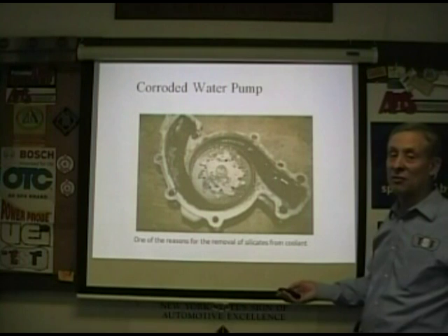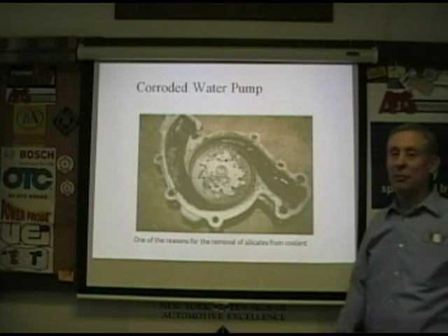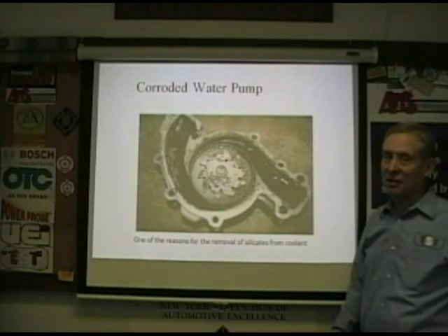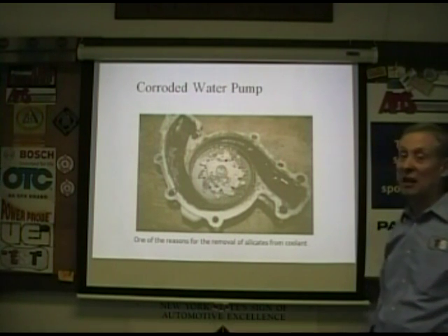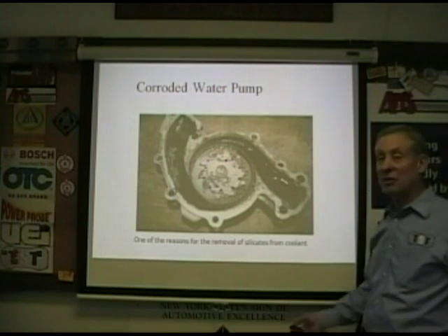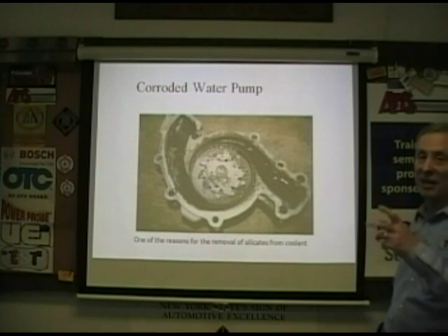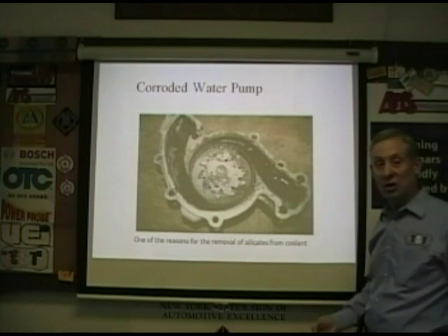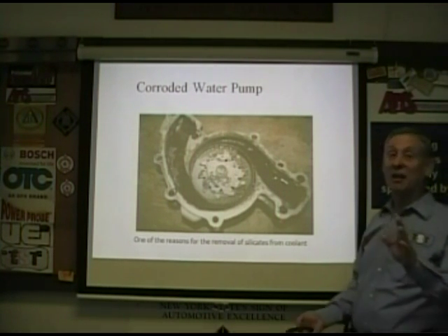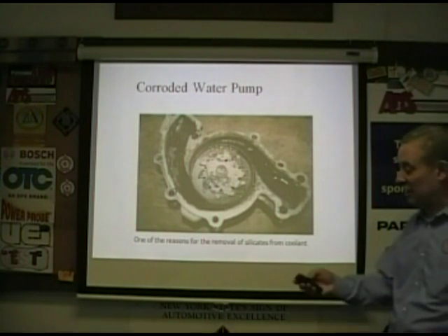And of course, with modern cars, we have the plastic impellers. VW has them, BMW had them, and you end up with compatibility issues. Some of the time, that stuff isn't breaking just because the plastic was garbage, which it was, but some of the time it was breaking because people put the wrong coolant in and it weakened the plastic. It made it brittle. Or put some additives in so there were solids or precipitates that it couldn't push, and it was flexing that thing and breaking it.